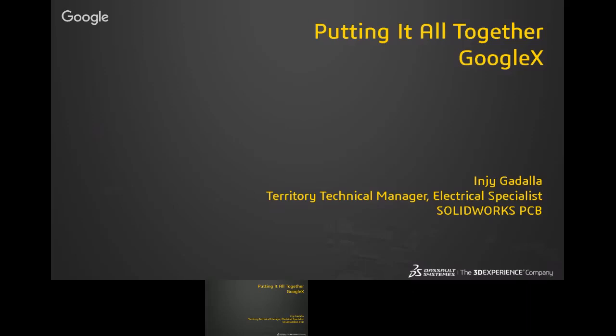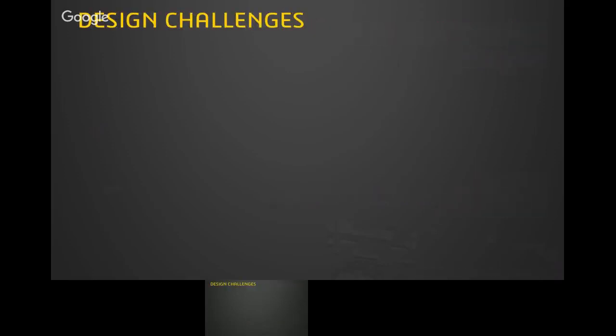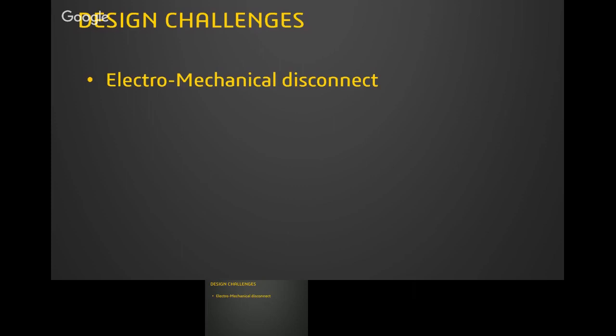So what we came up with is that there are challenges between the multiple divisions. So hardware, electrical, and mechanical, there are barriers. There is very little communication. Even if the communication happens, it's through what I call a snapshot of the moment of the design. So communication between electrical and mechanical happens through DXF. You transfer board information to get the outline into your electrical environment. You place critical parts, you export a STEP out, and then you give it to the mechanical team, they bring it in. These are challenges that are very common today between different divisions.